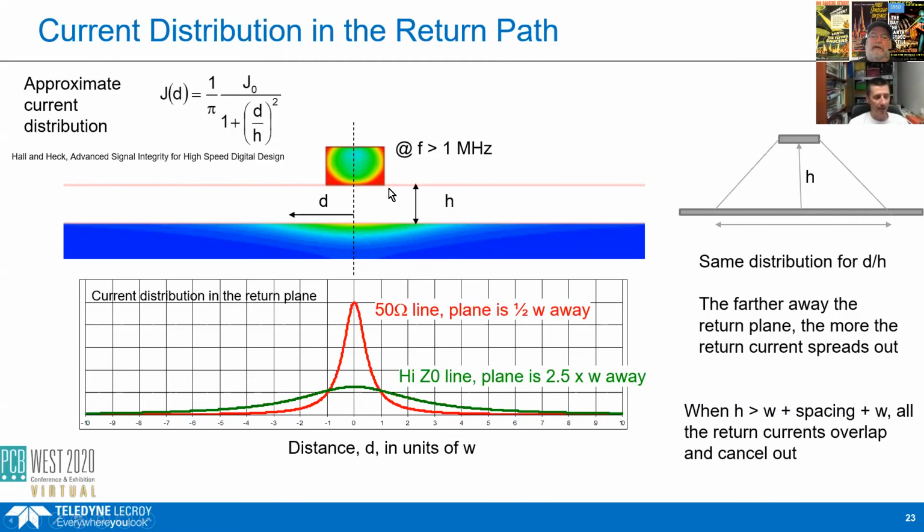It means the current basically flows on the surface of the track. And as we go up to higher frequency, the current is going to flow more to the outer surface in the signal line. But it's confined, it's got walls, so the conduction current can't flow outside. And so we're looking at conduction current here. If we have this changing voltage, then of course we'll have a displacement current between the signal and the return as well. But we're just looking at the conduction current in the conductors.